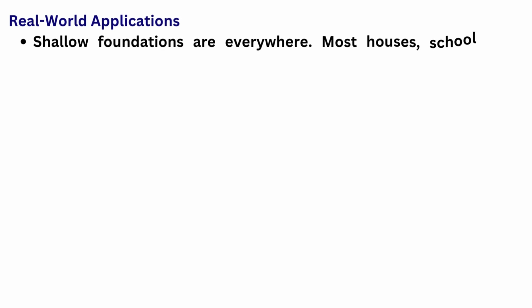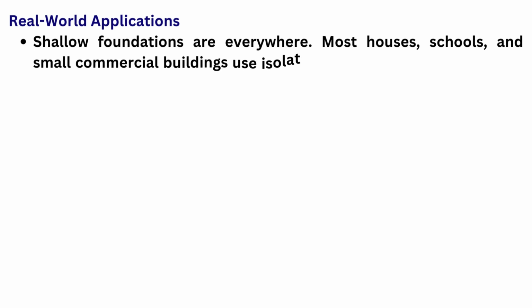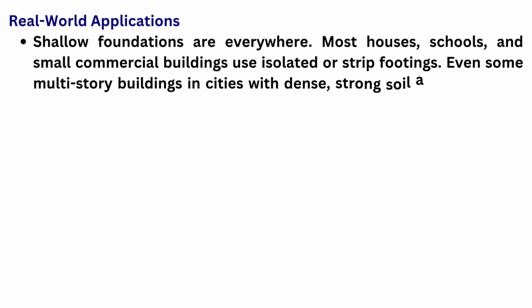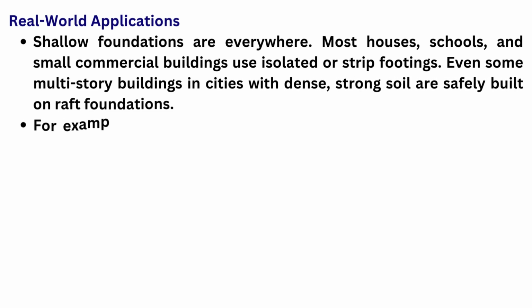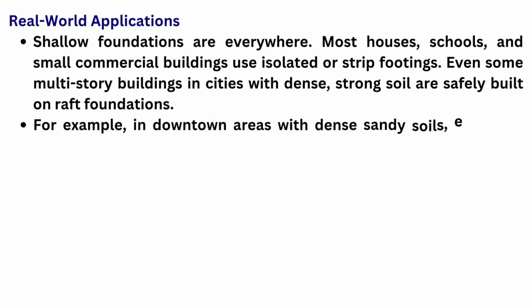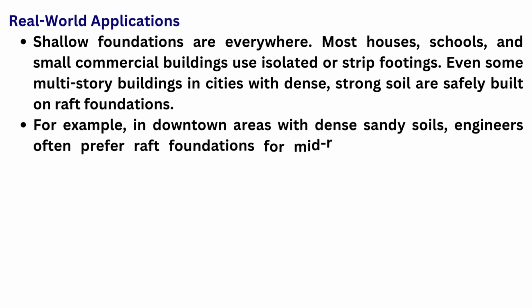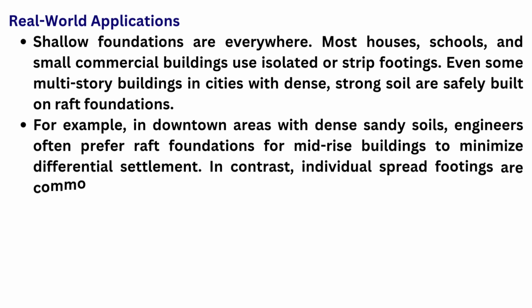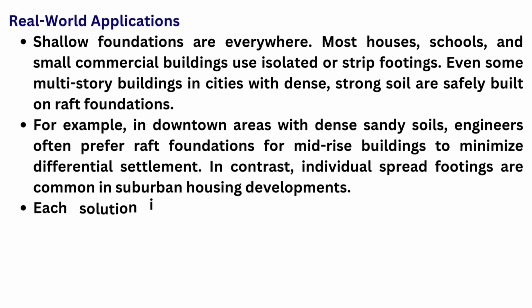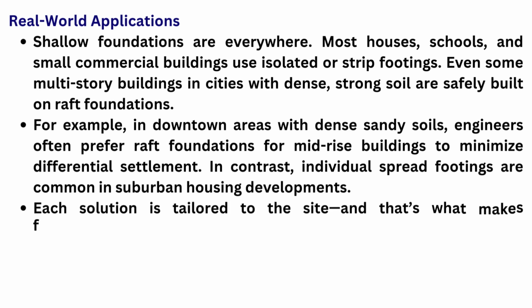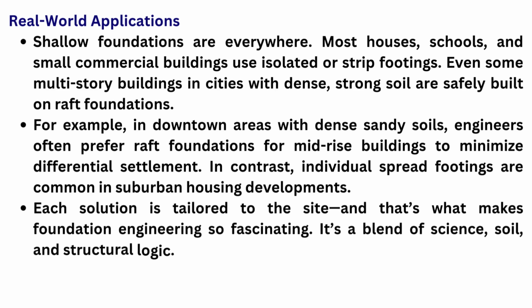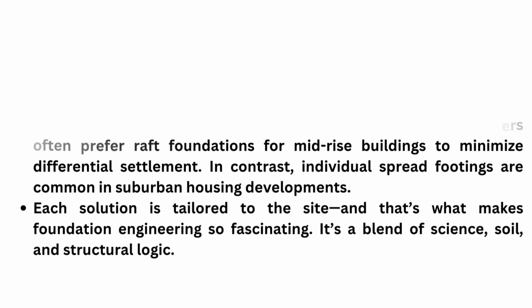Real-world applications. Shallow foundations are everywhere. Most houses, schools, and small commercial buildings use isolated or strip footings. Even some multi-story buildings in cities with dense, strong soil are safely built on raft foundations. For example, in downtown areas with dense sandy soils, engineers often prefer raft foundations for mid-rise buildings to minimize differential settlement. In contrast, individual spread footings are common in suburban housing developments. Each solution is tailored to the site, and that's what makes foundation engineering so fascinating. It's a blend of science, soil, and structural logic.